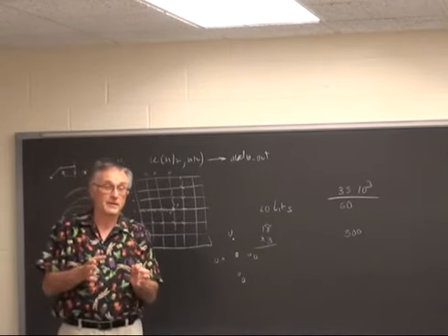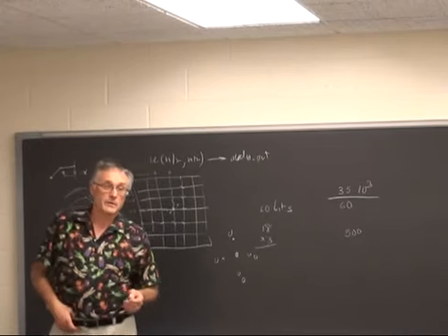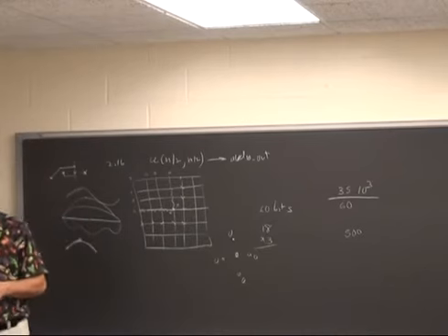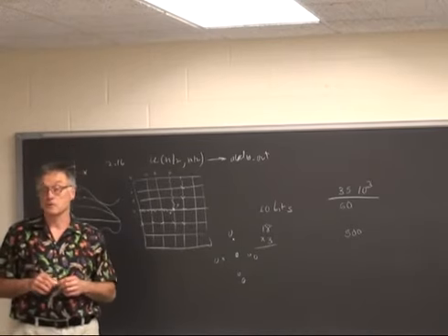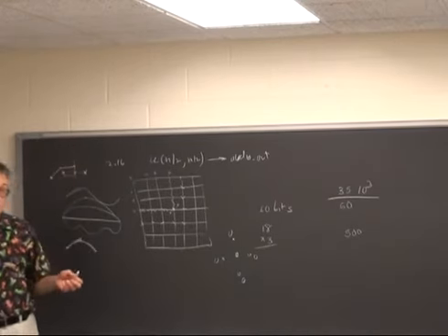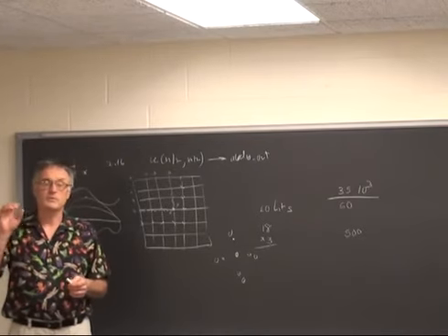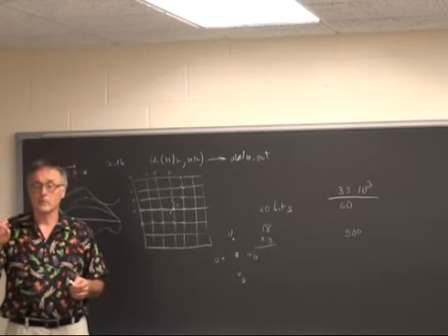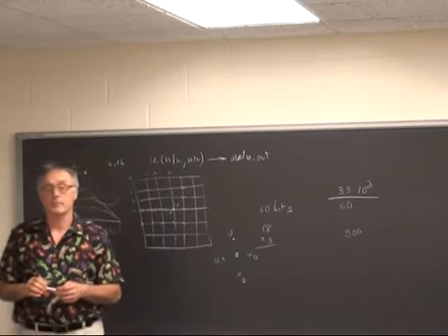The basic hardware multiplier is a 9-bit unit. So if you're going to go above 18, you should probably go to 27 bits if you're using multipliers. If you're not using multipliers, then it absolutely doesn't matter; you can use 23 bits or 22 bits or anything you want. You'll get better resolution, you'll get better sound at low amplitudes. Then you'll get more accurate attenuation at low amplitudes, and it won't matter at high amplitudes.